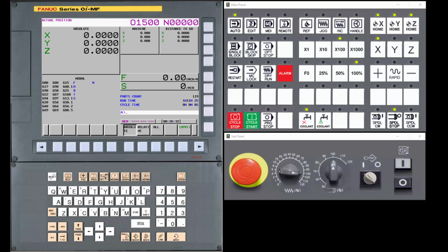One of the most important CNC maintenance tasks is to make a backup of all the user files. This includes system parameters, the PMC ladder interface and parameters, custom macros, ball screw error compensation data, and several other files that may vary from machine to machine. These files are mostly created by the machine tool builder, but they are sometimes modified by the machine tool distributor as they integrate the machine with other devices, and then again by maintenance engineers at the end users. They are all essential to the accurate and productive operation of the machine.